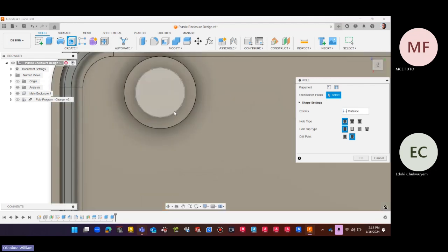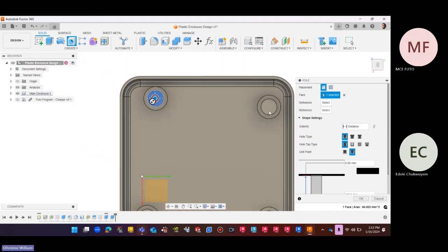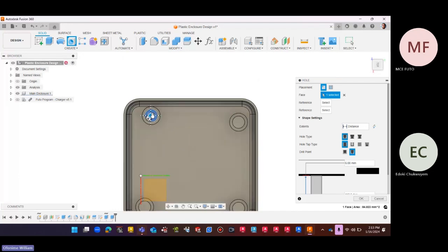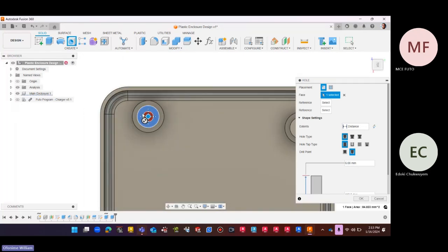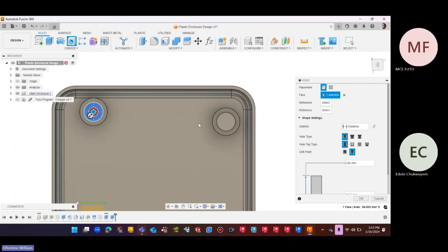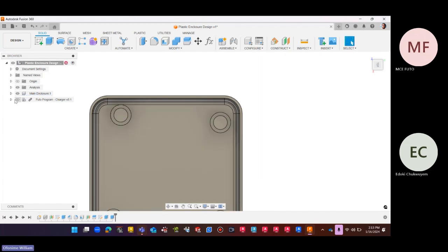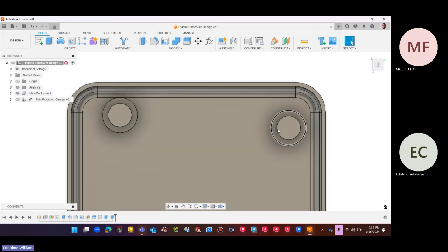then you just do a selection. Now I want to do a multiple selection, right? You see, it's not letting me because it's just trying to align to just one circle at a time. So how do I get this done? I could play a little trick here. Cancel this command, go over to the sketch. We don't really want to use it as if we are using it to sketch something, but we just want to reference or use that center. That's what we use in creating these buses.